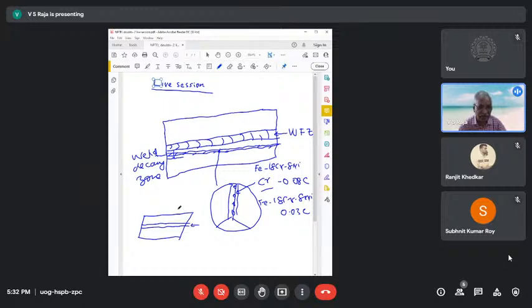And please notice this is a carbon steel, and it is not a stainless steel. So we are not going to talk about weld decay. We may still talk about the heat affected zone, but the heat affected zone generally is not a problem in low carbon steels. If the strength is low, it's not going to matter much.